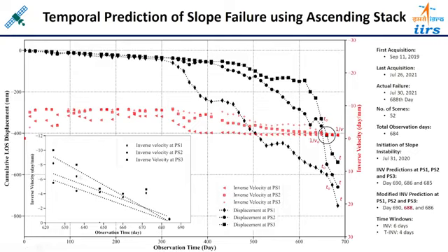and then the regression line was fitted, and then the extrapolation was calculated from the time axis. So basically that is telling us the time of prediction. By this calculation I have observed the inverse velocity method prediction at all these 3 points is 690th day, 686 day and 685 day.